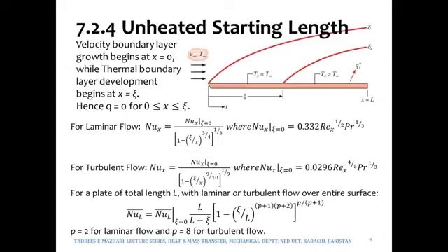So we have a box, and inside the box we have a black colored absorber plate. When the air starts flowing, the fluid will flow over that plate, and in the beginning it will not get heated up. Therefore a flat plate collector may be considered as a case of unheated starting length,